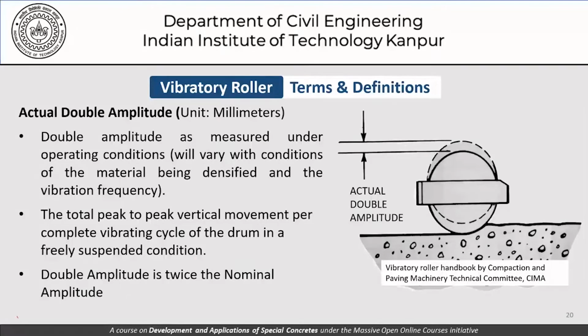This picture shows a schematic representation of the roller. You can see here that this roller wheel actually oscillates between these two positions, and the bottom is shown here. As it moves in one pass, it is trying to compress, or cause settlement, in the layers ahead. So if this process is repeated several times, we will have this concrete getting compacted.